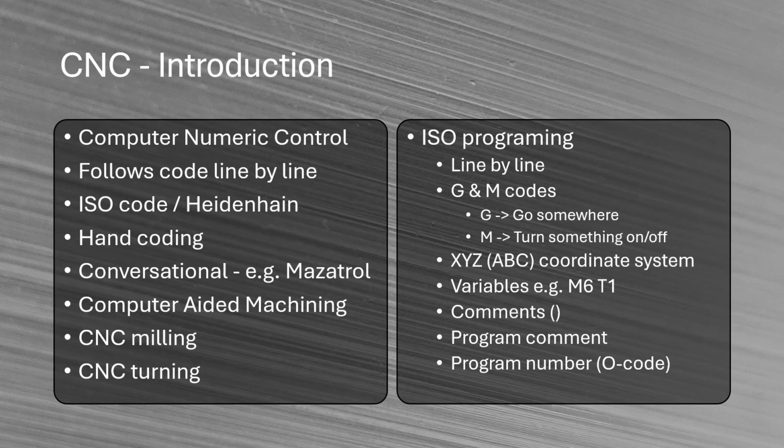For example, on Mazak machines, they've actually turned that into the article number, which I think is really clever. So instead, if you had a part that's called TH1-001, that would be the O code, basically. But on old school machines, typically you start at 1001, then 1002, that's most common.